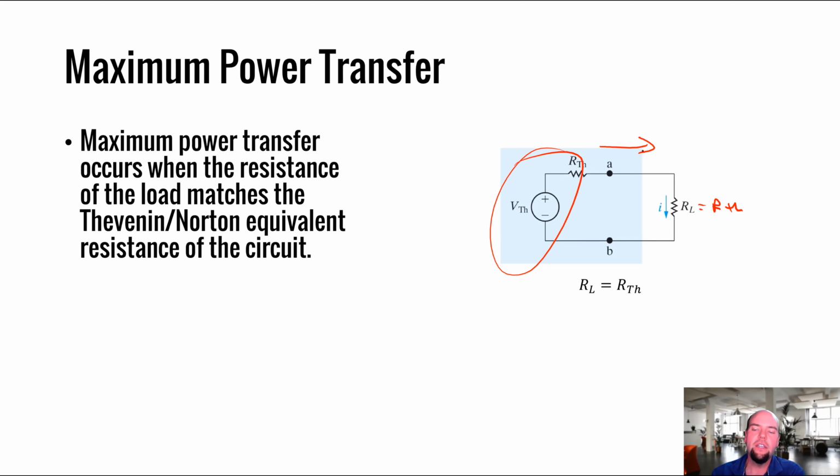And matched impedance, well, you'll call it impedance later on, but for now you can call it matched resistance. That is this concept of when you have a powering system coupled to a power drawing system, the way to get a maximum transfer of energy is to have their resistances be matched with one another. And this is a concept that's going to show up again and again and again. But maximum power transfer, very, very important concept. And you can find it.